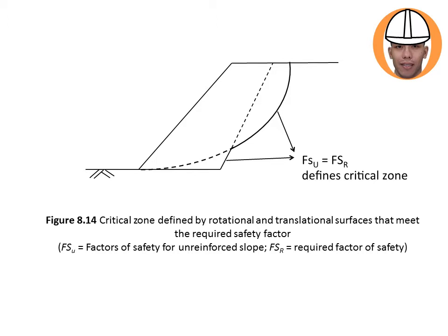So that is the theoretical failure, the failure plane made into the slope. The simplest form is usually the plane or the wedge kind, which is using a straight line. But here you can see we have an arc of a circle.